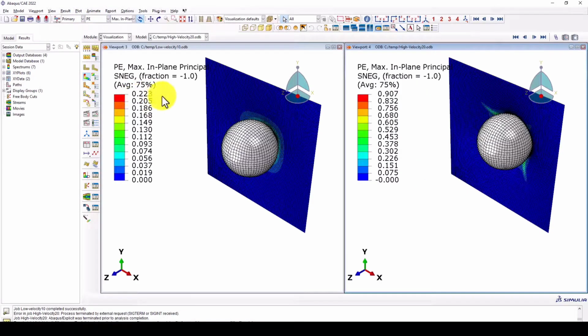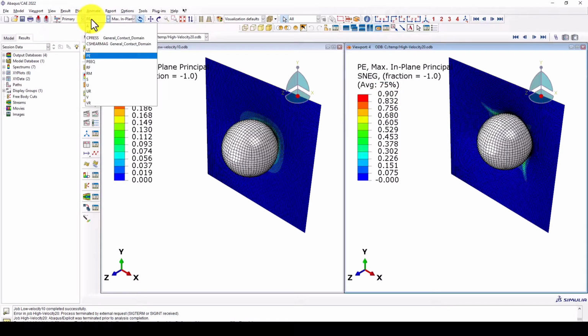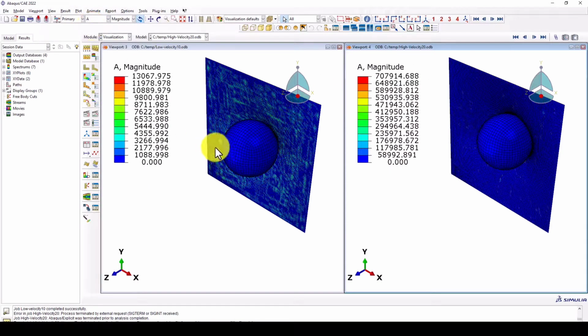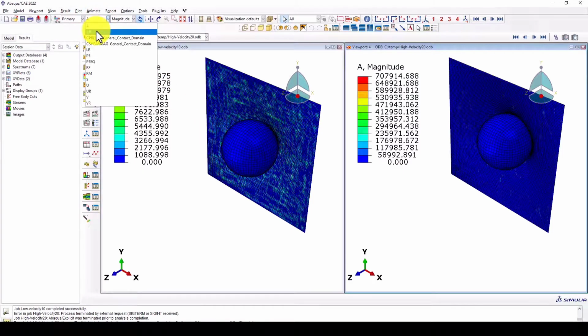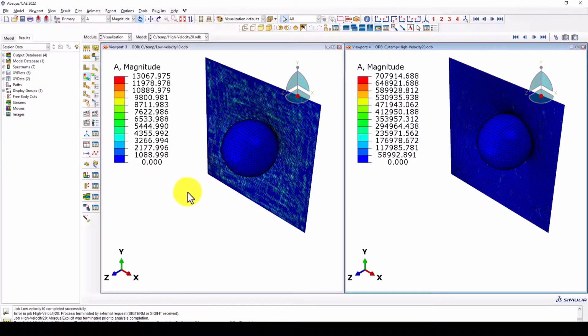So the most important takeaway in this simulation study is that impact simulation is not simply about applying a large force in the numeric input values. It's about correctly representing mass, velocity, momentum, contact, material behavior, deformation, and transfer of energy. And when those physics are modeled correctly, Abaqus Explicit becomes a very powerful tool for understanding real impact problems.